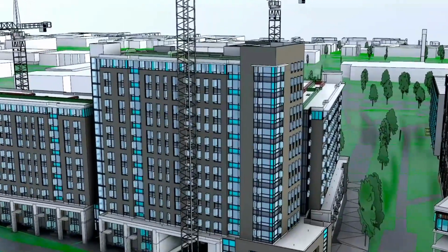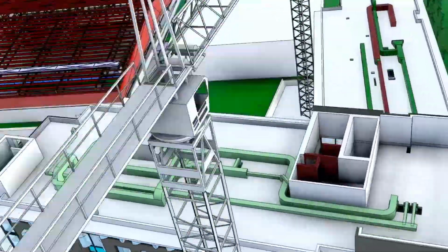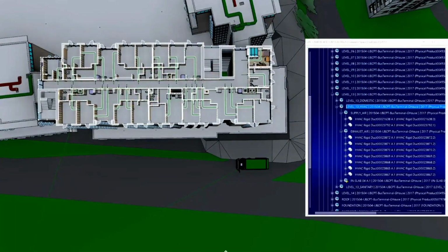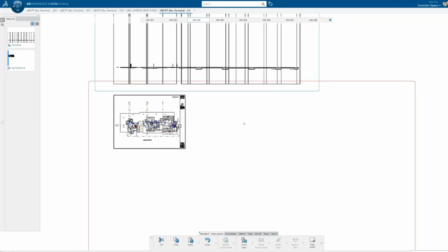One of the main challenges of this project was the coordination of the horizontal in-slab ductwork and vertical plumbing risers throughout the tightly packed units in the tower. From the initial layouts provided by the design team and integrating the detailed stud wall buildup, we were able to coordinate and optimize with the trades the typical suite layouts to eliminate construction coordination issues while also improving consistency by reducing offsets and overall time required to install.